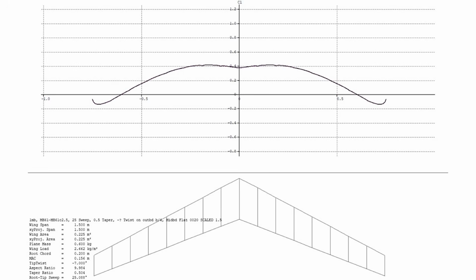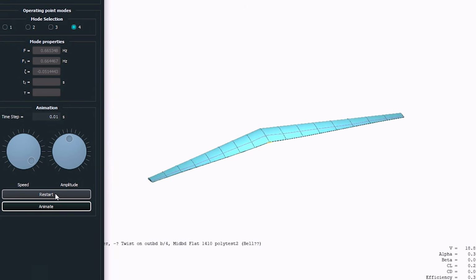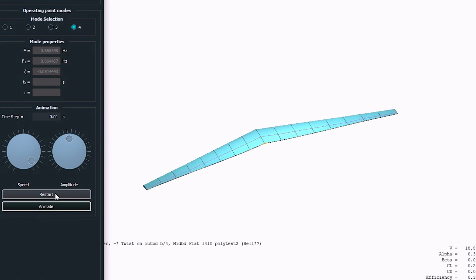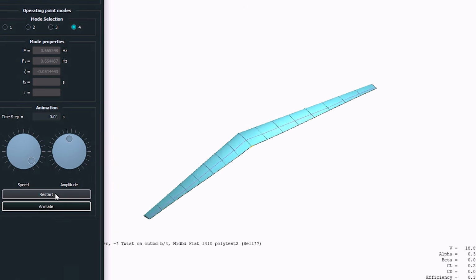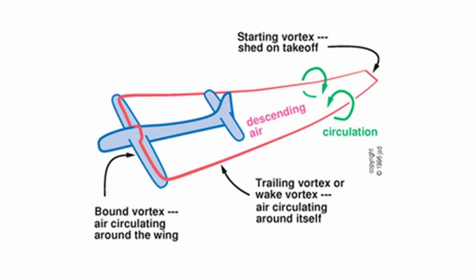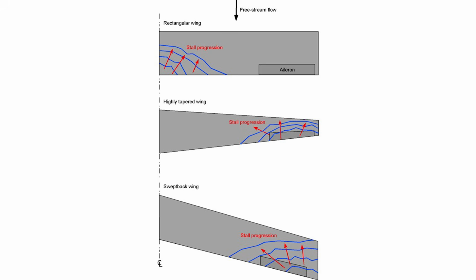But with washout, we can also improve lateral stability, or the yawing moment, which will be especially important at low Reynolds numbers and high angles of attack here. Washout also delays the onset of stall at the wingtips, which means that the aileron or elevon control authority can still be maintained when the root of the wing is stalled at higher AOAs. Swept wings in this application tend to stall at the wingtips first due to the lateral boundary layer flow, so the washout in coupling with this can reduce or eliminate this.